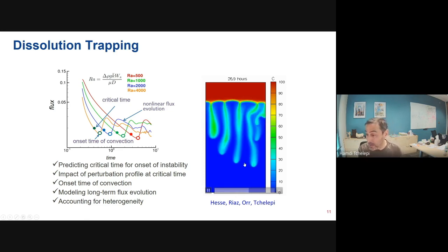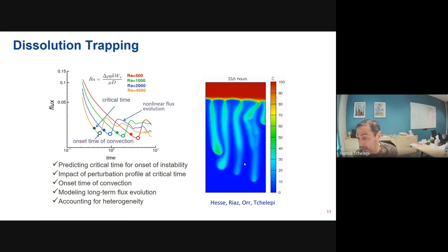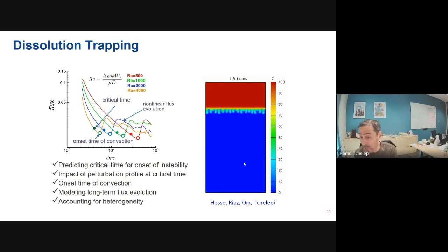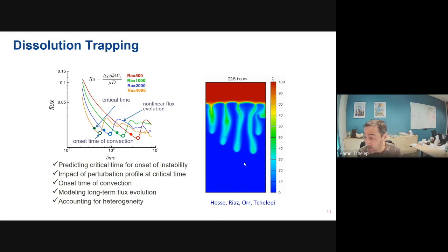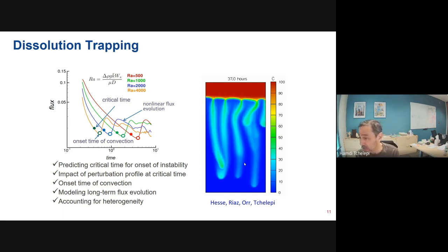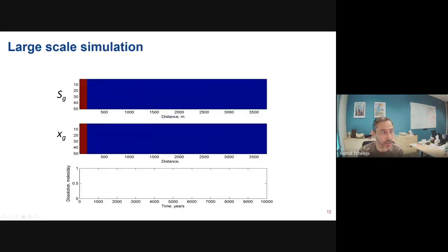So in order to understand this gravity-driven instability, you have to resolve the length and time scales that would allow you to resolve the initial perturbations, but also the length and time scales and the right numerics to be able to model these convective fingers accurately. So that places a huge burden on the numerics that you can put together.